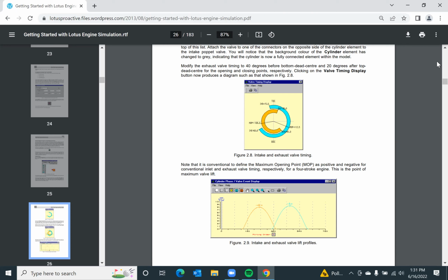Because please try to understand, fluid will flow from higher pressure to lower pressure. So what it means is, if you want to control the flow direction, you need to have that pressure differential, and that totally depends upon where the piston is. Everyone understood this? So you will have to do this mapping.